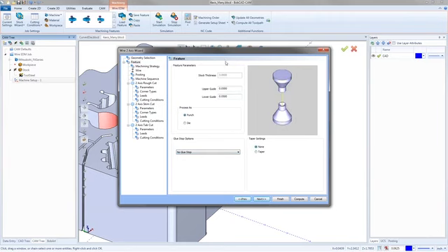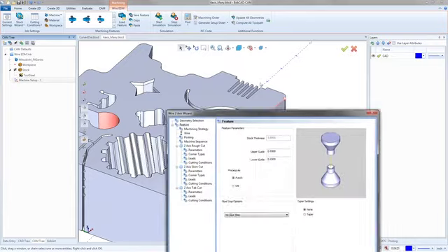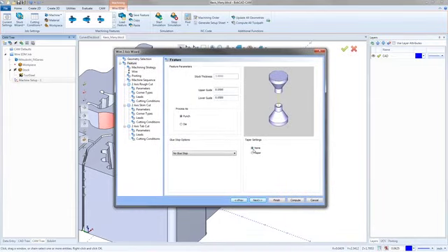And then our taper settings. That should be a straight wall. From every time I've ever cut it, it was a straight wall. So I'm going to leave it as none right now. We'll keep it simple. And so it's just going to be a straight cut right along that wall.